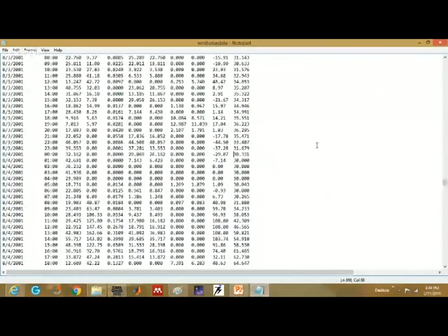30.33 is the state of charge, and you required minus 29 kilowatt power from it. So the battery cannot give you that, because you have put a constraint of 30 kilowatt. Some other source has to supply it. Now you see the generator will be there somewhere. See, the 6.49 is from the generator, right?